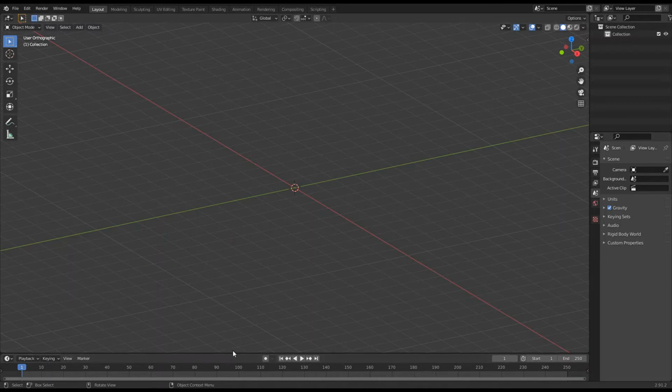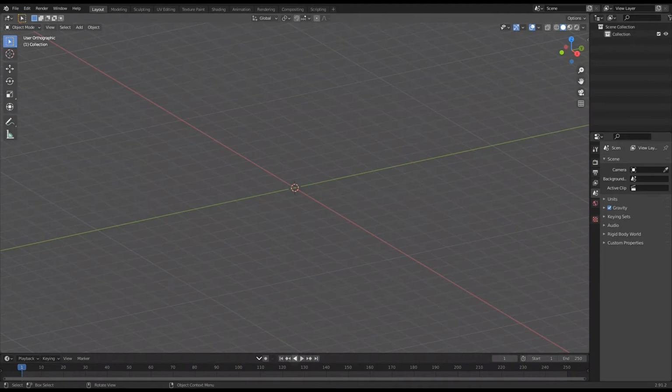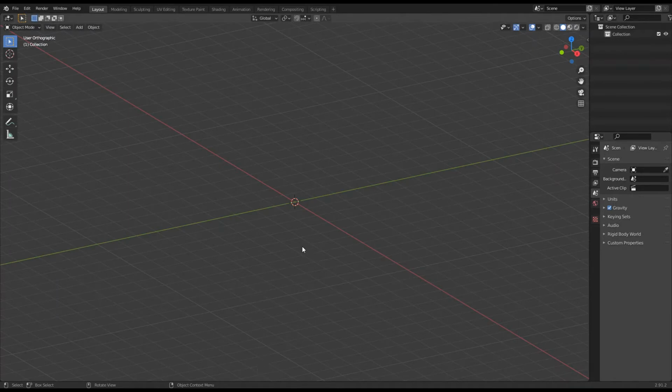And now I want to get rid of this as well, so I move down until the cursor changes into a double arrow, right click, and then it says Join Areas, go Join Areas, and then come down over the timeline and click. And the top window gobbles up the bottom one. Right, so that's a nice clean work area, and that's what I want.